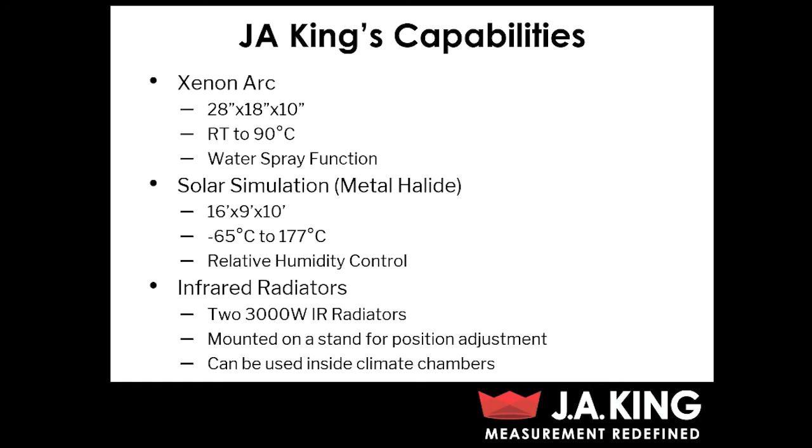And then we do also have infrared radiators as well. We've got 2 infrared radiators on stands. Both are 3,000 watts. And they're mounted on a stand on wheels so that we can adjust the position however we need to. And then the radiators can actually be placed inside a climate chamber as well so that we can control the ambient conditions of the test.